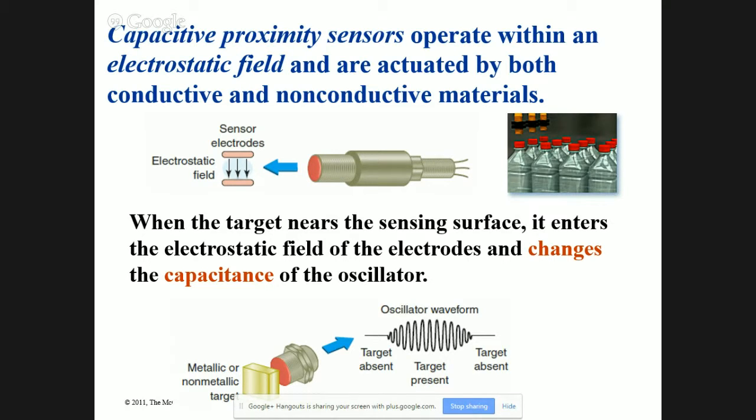This talks about how they can work off plastic. You can have sensors that sense plastic, and sensors that sense metal. You can get color-sensing photo eyes with a teach button. Let's say you've got a label on a product and you want to make sure the label's on there. You adjust the sensor to teach it a color on the label, maybe a blue spot.